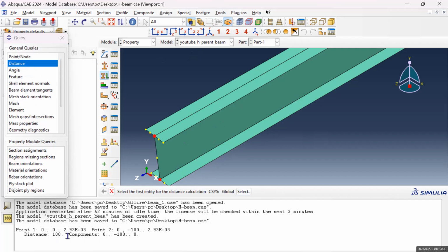Okay. And then the width of the stiffener. The stiffener should occupy this area from here to here, like in the middle. You have to know that the stiffener is a plate which we use as a vertical reinforcement, so it should occupy the whole area of this flange.